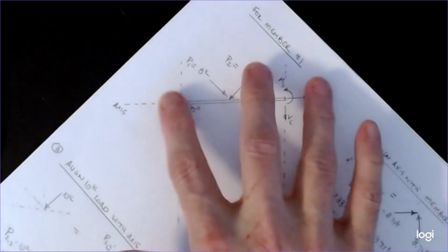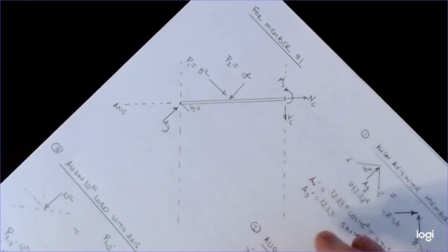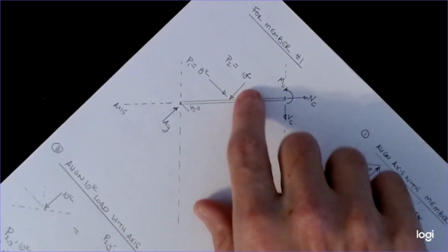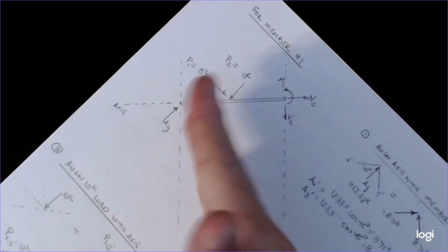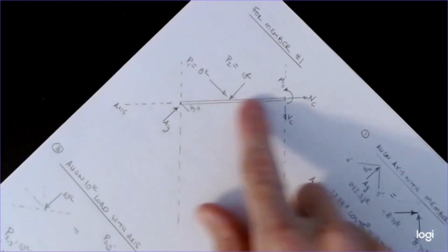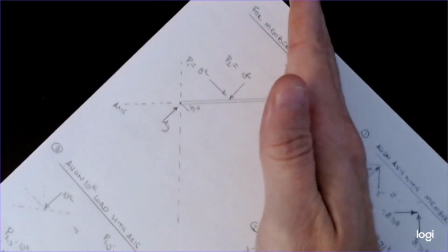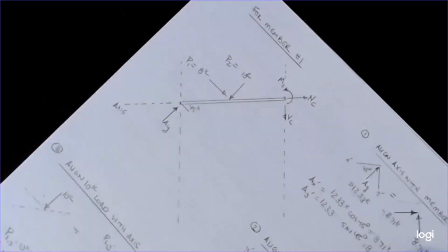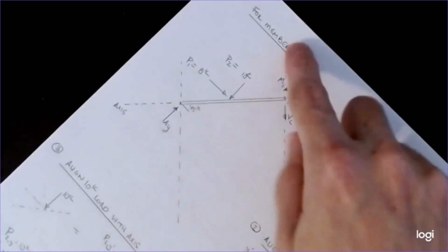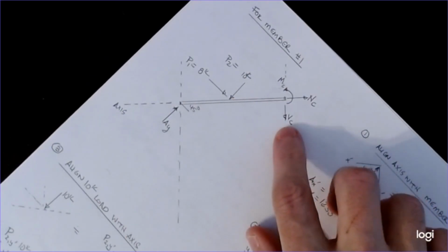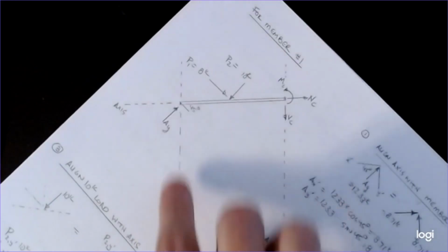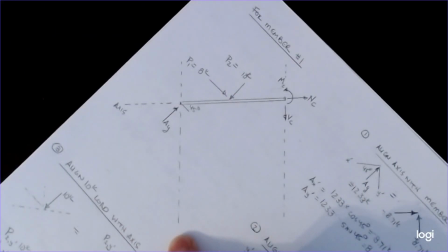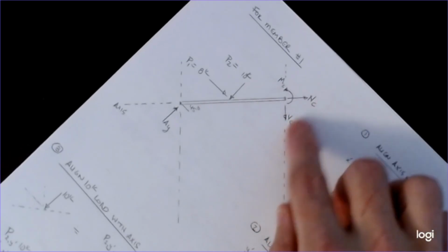To be able to draw shear moment for this member, I've got to find those internal forces at the joint, or just before the joint, if you will. Now, part of the problem that we have is if I incline my paper, now I have forces that don't line up with the coordinate system. All the other problems we've done to this point, my reaction is always aligned with the axis of the member, which is this line coming along here, and then these perpendicular lines that we use to help segment and set up the graph. And so we've got to get all of these guys turned to align with this system. You have to do this step because VC and NC are always aligned with the longitudinal axis of the member and the perpendicular line that comes across the section. And so that's why these are oriented the way they are. That's the trick. That's the difference in this.